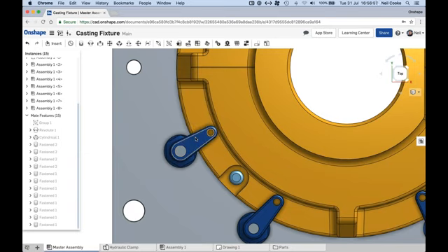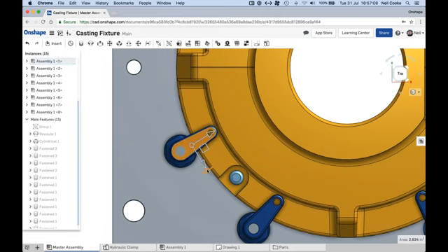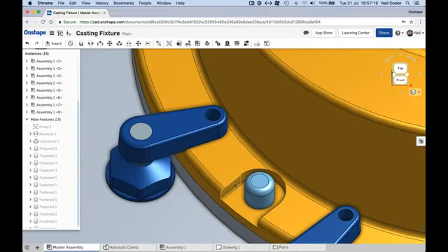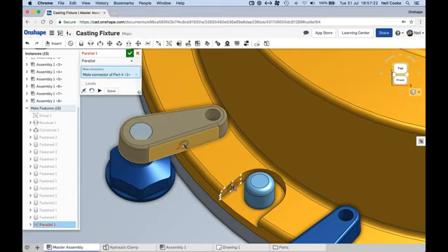So in order to control the position of that, you would have to add another mate at this top level in order to control that. If you have it in one orientation, and you wanted to get it roughly right, say it's 15 degrees from where it was, you can use those manipulators. But if you want to make that parallel to this face over here, for example, then you could say, let's make that parallel with this guy here.